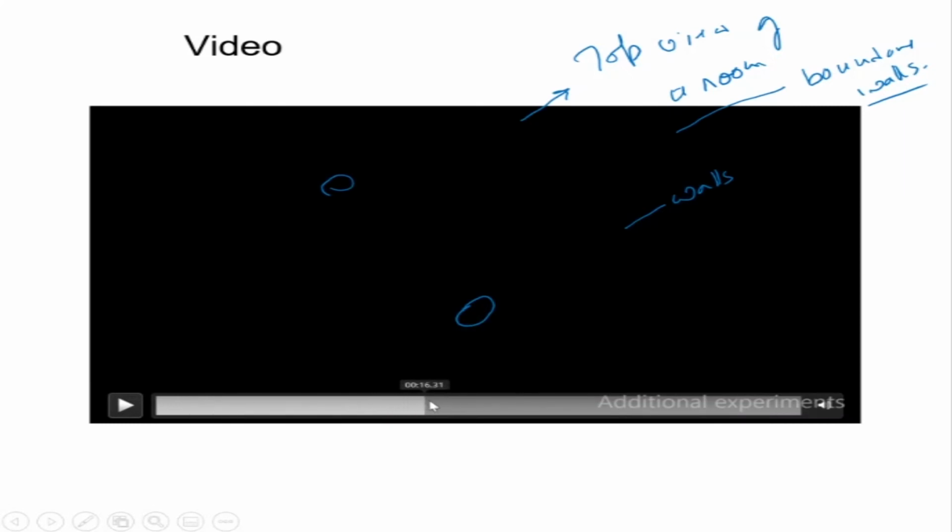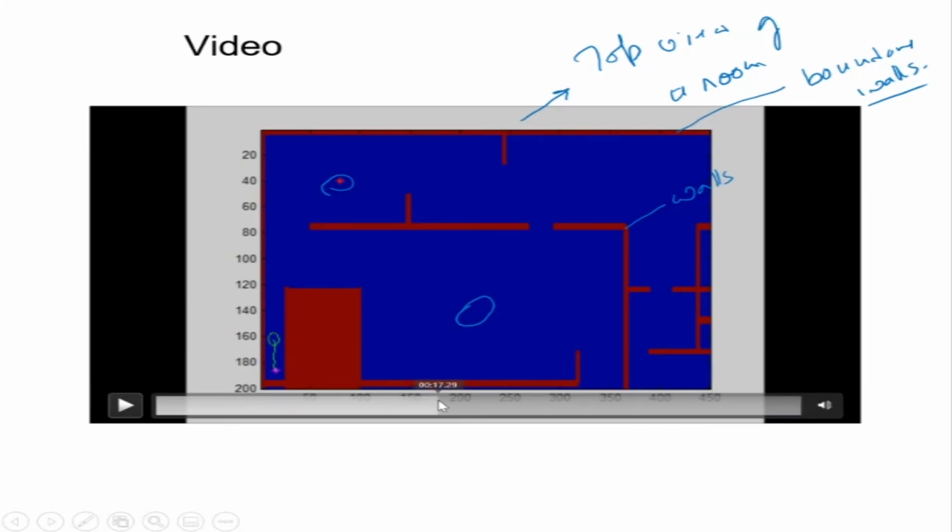Here the robot is positioned here. So let me rub this out. So in this particular case, the robot is positioned here. The goal is still the same point. Okay. Now simply by assigning potentials, the robot is moving. You can see from the narrow passage it is going out towards the goal and reaches the goal. Now we choose another location. Again, you can see the robot has moved. Now we can choose another location which is on top there. It is avoiding the top wall, coming and then reaching the goal.